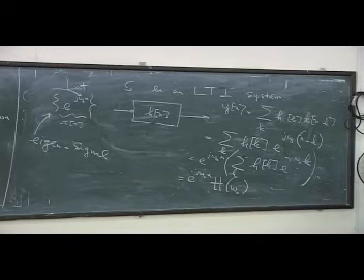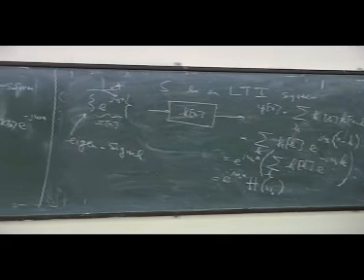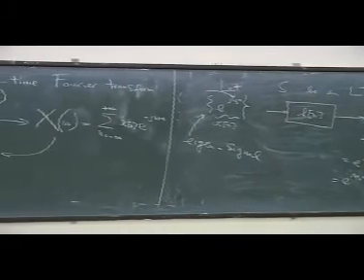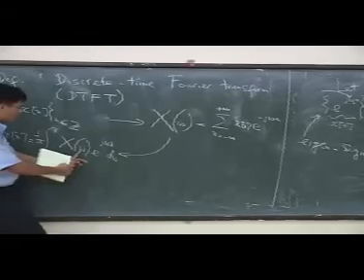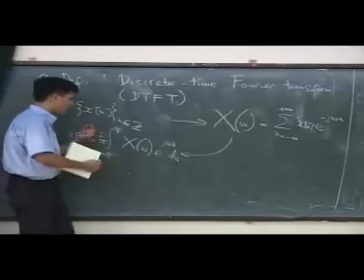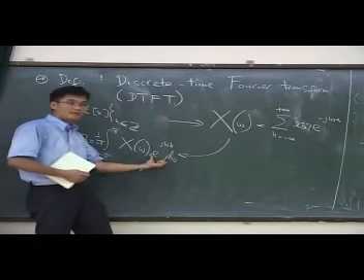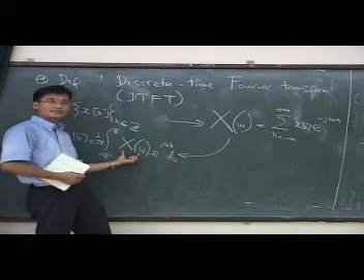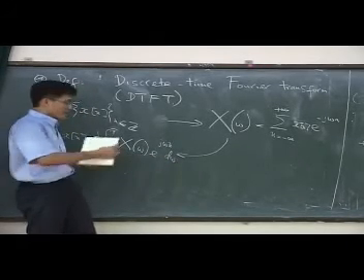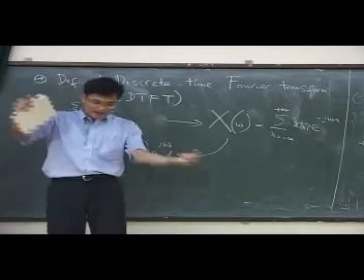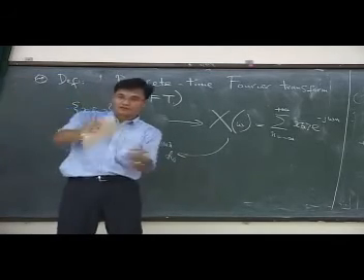So go back to this formula. You have a signal, and because the signal is infinitely long, my summation is now an integral, loosely speaking. I have all of this X(omega), which for each particular omega is one particular signal, and that's the weight. So I have a signal, I can expand it into the Fourier basis, different components.